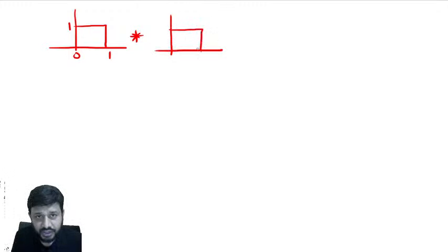I am giving you the idea. Suppose I want the convolution of these two signals. Now can you find out the convolution of these two signals using Laplace? Yes, we can find out. Observe here. If you want to find the convolution of these two signals, calculate their Laplace, multiply their Laplace. To the resulting Laplace transform, find out the inverse Laplace transform, that is nothing but the convolution result.